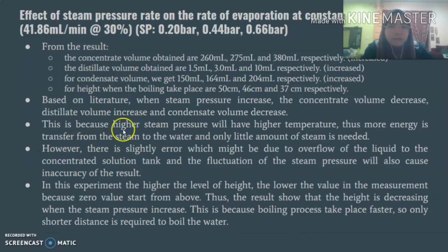However, there is a slight error in the result obtained, which might be due to overflow of the liquid to the concentrated solution tank, and also might come from the fluctuation of the steam pressure, and that will cause inaccuracy of the result.